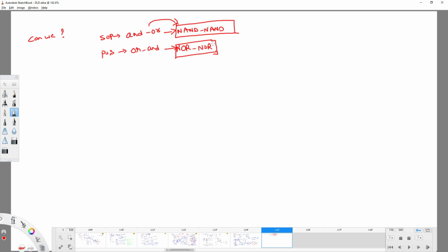Or else, whatever equations are possible in NAND or AND OR, can we implement all of them using multiplexers? The answer is yes. Let's move on. Why? So, guys, why am I saying that AND OR gates I can implement with the help of any other gates? The reason is this: AND along with any kind of NOT gate is functionally complete.